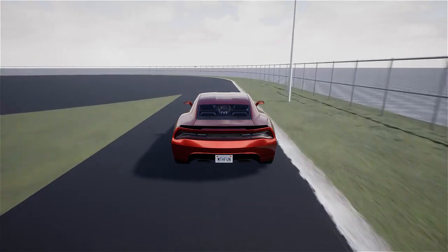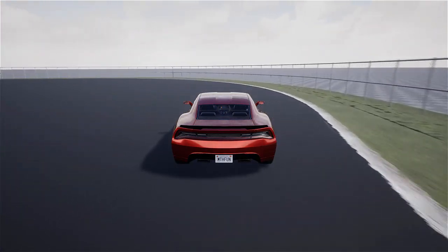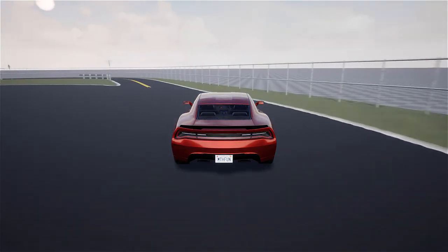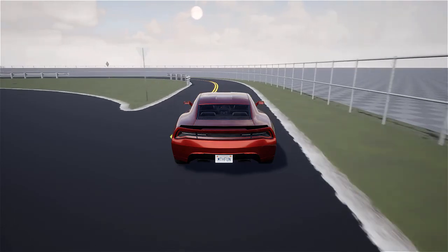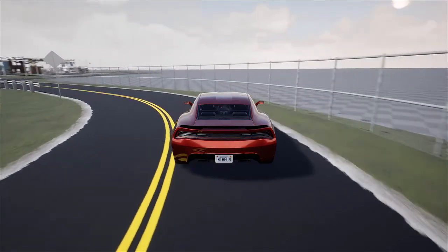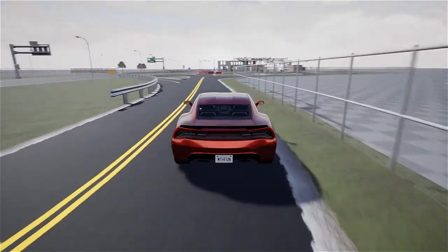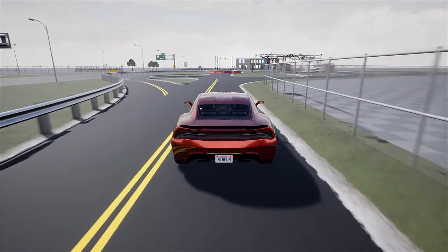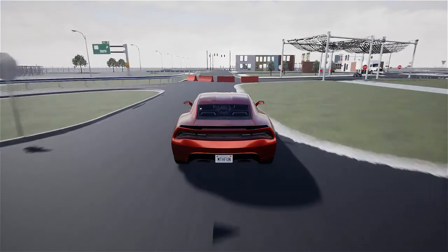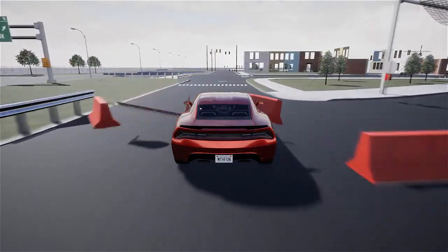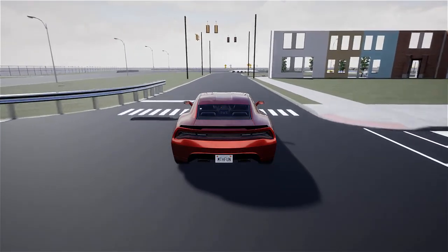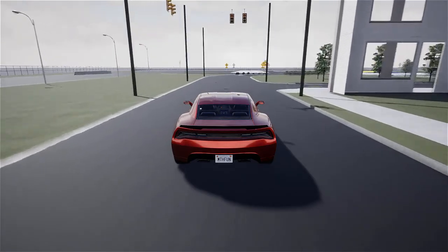You can also log signals from the controllers and the vehicle for post-processing. It is also possible to tune parameters while driving. For instance, if you were to tune the controller gains to feel how that influences the drivability of the vehicle. Over there we can see a few red barriers coming up. As the car drives through them, we can see them move. This is done on the Unreal Engine. The vehicle physics is done on the Speedgoat real-time target machine.